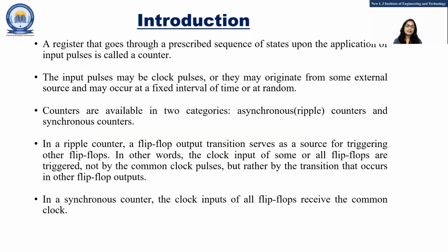So as I have discussed in the previous video of asynchronous up counter, what is the difference between asynchronous and synchronous counter, and what is the up counter. Okay, so I will just give you a reminder that in asynchronous counter, the output of one flip-flop will be given to the next flip-flop as clock pulse. And in synchronous counter, we will give clock pulse to all the flip-flops simultaneously.